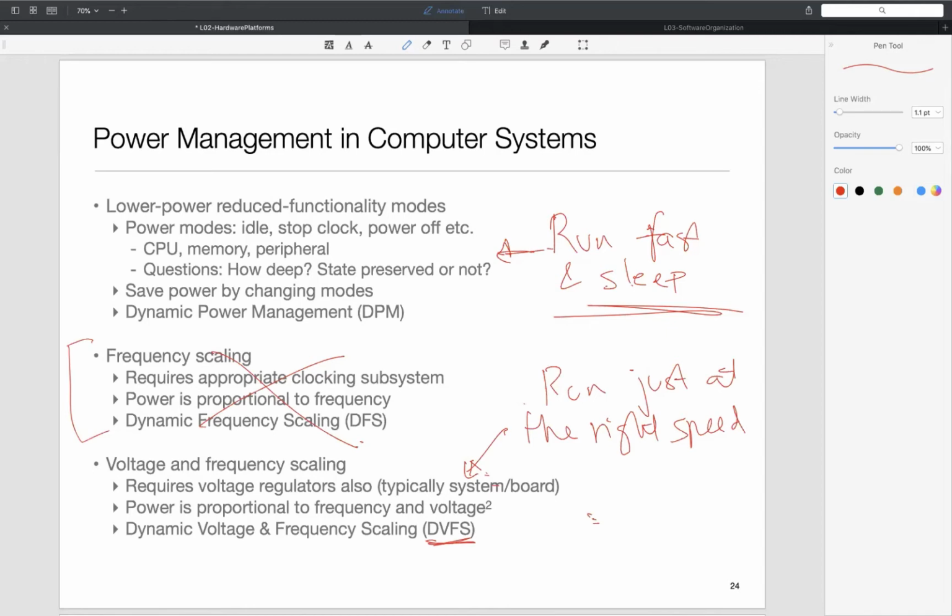So you would see optimizations of timers and things like that. Often, like in Linux, you would hear something called tickless timer, and Mbed also has a tickless timer. The idea is, if you're going to sleep, then try to sleep as long as possible. Don't let the OS wake you up. Don't let the clock wake you up, for example. So a lot of optimizations are done towards that. Okay, any questions on this?